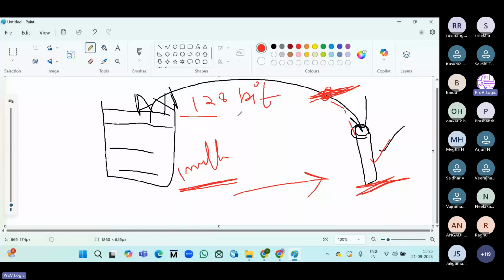So it will get small amounts of data in terms of bus, like 32-bit one time, the next 32-bit in the second transaction, the next 32-bit in the third transaction, the next 32-bit in the fourth. Like that, small amounts of data will be sent to this block. That's exactly what AXI to APB is, and this bridge will control the address and the data.